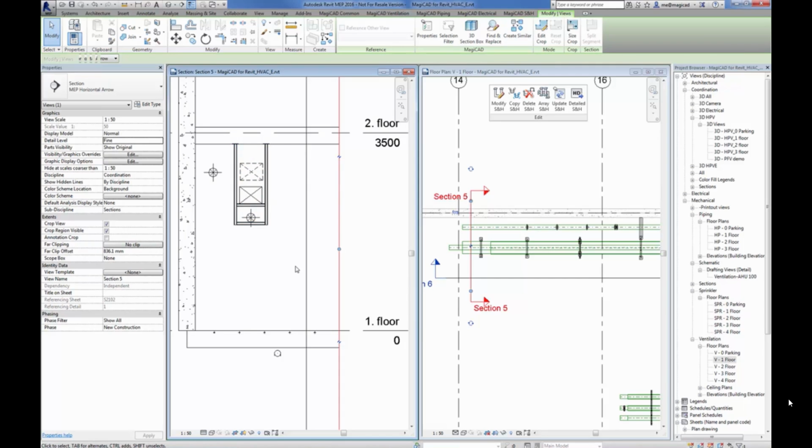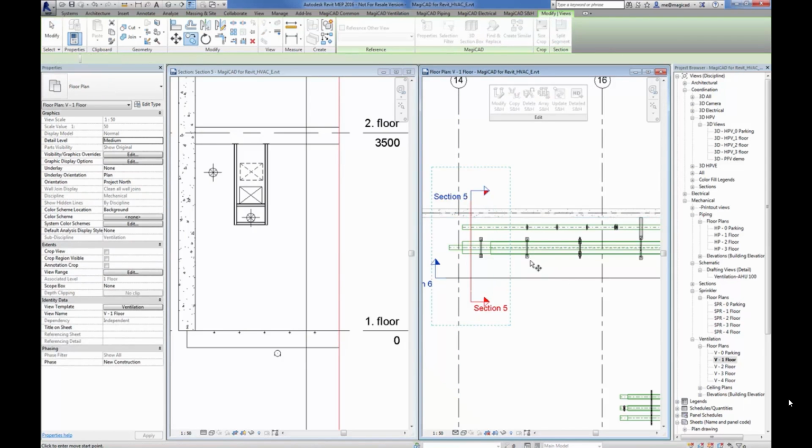So there's a slight difference between copy with Revit copy and copy with supporting hanger. You can also copy with Revit copy, and it also has some smart functionality so it adapts to the situation. But with the Revit copy you cannot add additional objects as I did in the previous case.